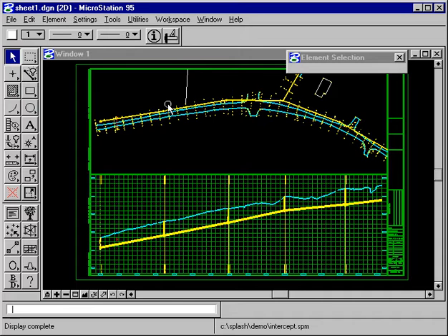We've been able to lay out all of our construction plan and profile sheets without the design being absolutely finalized and approved. So now that we've created these sheets, upon inspection we've realized we've made a design flaw. We've forgotten to put any drops through the manholes.